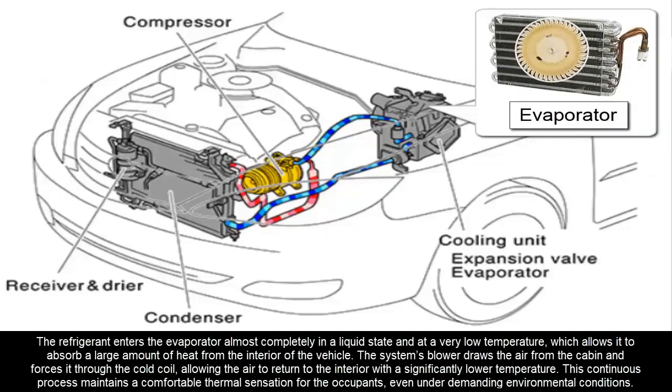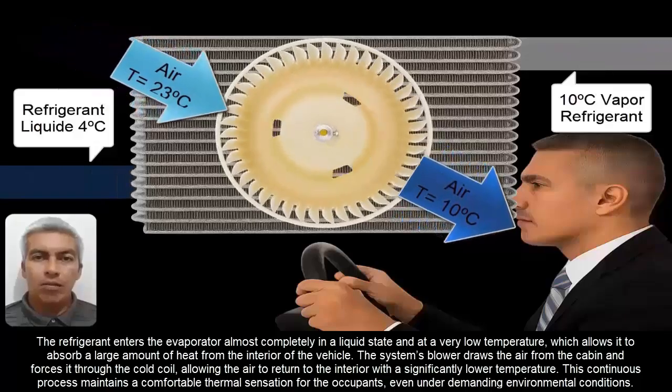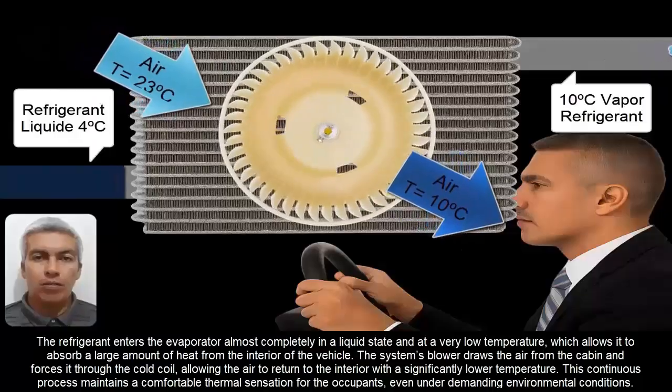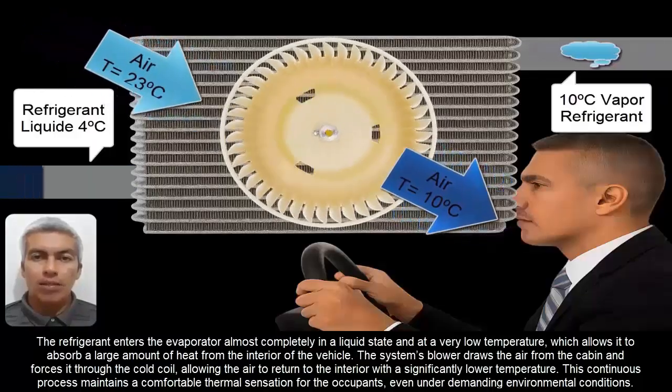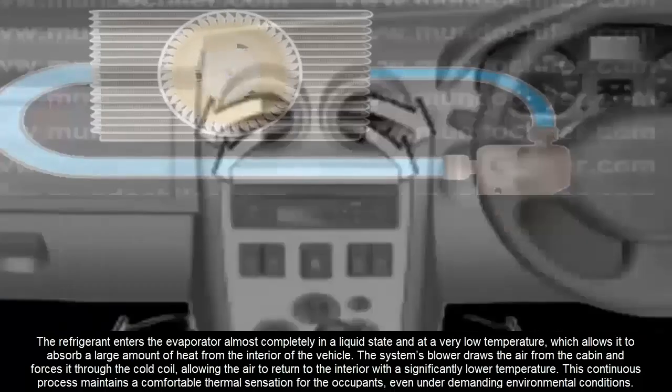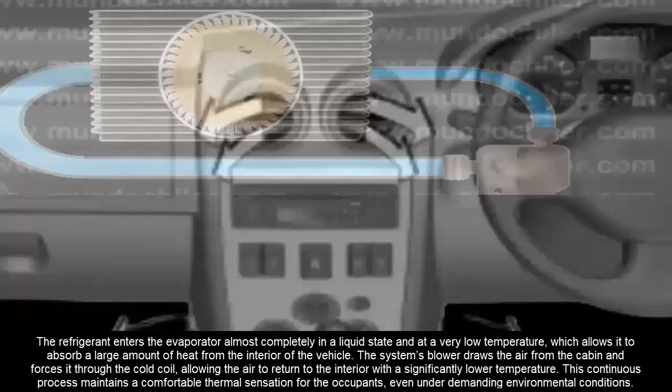The refrigerant enters the evaporator almost completely in a liquid state and at a very low temperature, which allows it to absorb a large amount of heat from the interior of the vehicle. The system's blower draws the air from the cabin and forces it through the cold coil, allowing the air to return to the interior with a significantly lower temperature. This continuous process maintains a comfortable thermal sensation for the occupants, even under demanding environmental conditions.